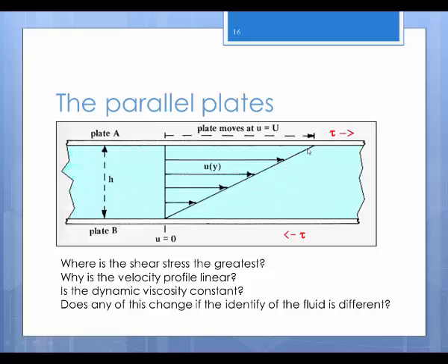So if you wanted to know what the force is here, you could say, well, find the slope of this line, find the dynamic viscosity of water at whatever temperature you're at, multiply those together to get a shear stress, and then shear stress is force per area. This plate we said was 1 meter squared, so if you multiply times 1 meter squared, you would get force in newtons or force in pounds force, and you would see this is how much force I have to actually pull this plate to get it moving at a constant velocity, as I mentioned up here.